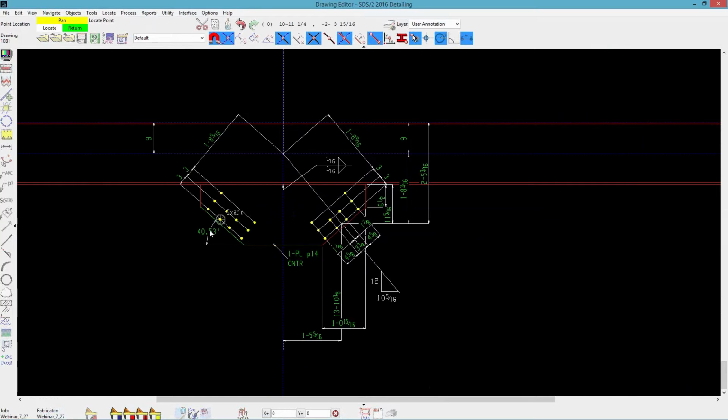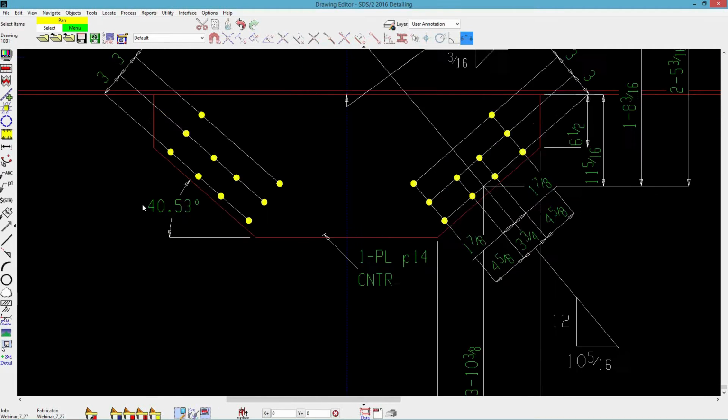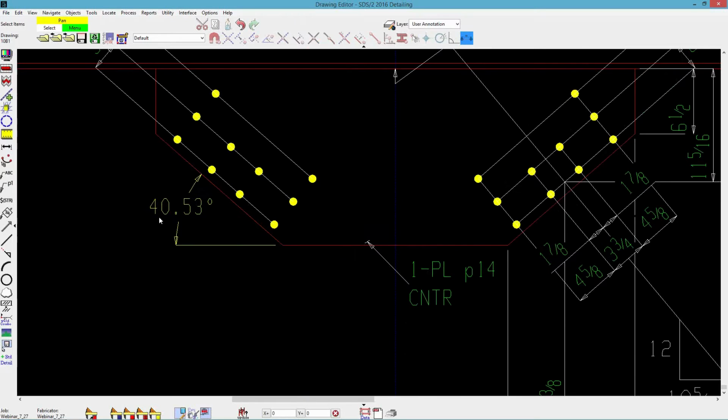And if I go and move between the quadrants, you'll see that my dimension changes. I'm going to pick this point right here. You can rotate by just left click and dragging your mouse. You can rotate that dimension. I'll come back to that in a second.